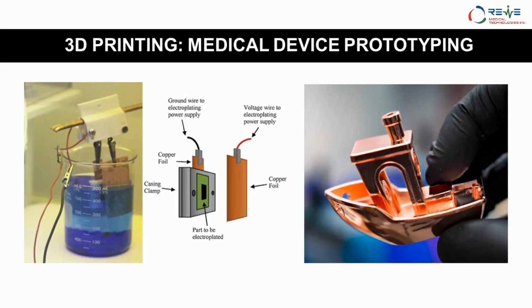Electroplating is another concept that is used to get a much more refined and much more solid part. Here you can say this is copper plating actually that's being done, and you've got a bath that has copper sulfate solution in it. It has two copper plates that act as the electrode, and your part is placed inside it. I worked a lot on this technique, and you have to coat a conductive layer on top of it.